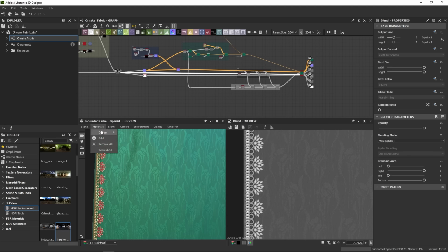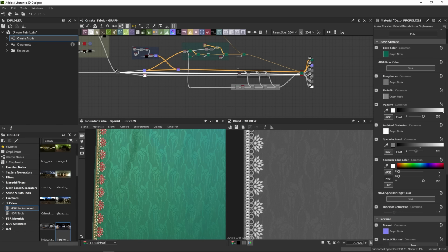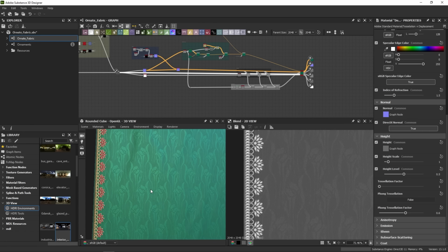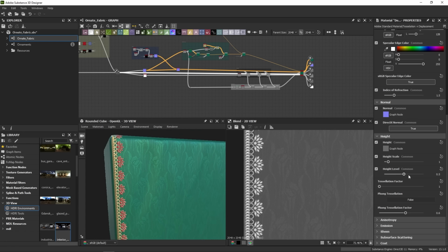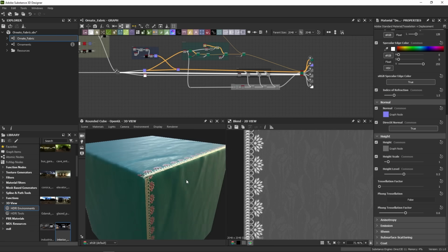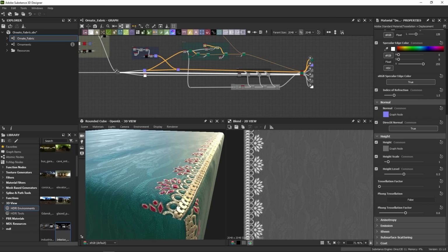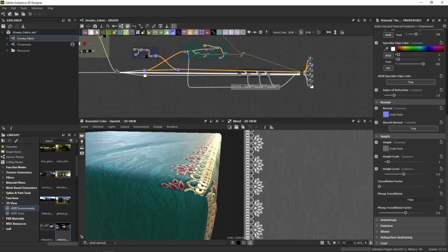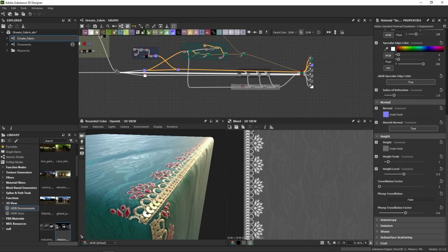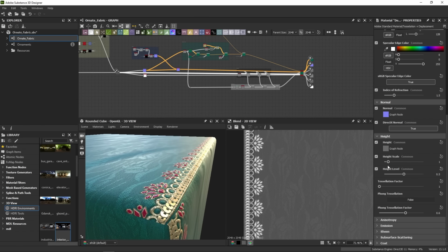Okay, so material, default, edit, and height. Designer actually went back to its default display settings with a little bit of displacement. You can see it if we look at it at very low angles. We have this sort of bumpiness on the edge here. And to see it better, we need to crank up the tessellation. Otherwise, designer will not have enough geometry to displace.